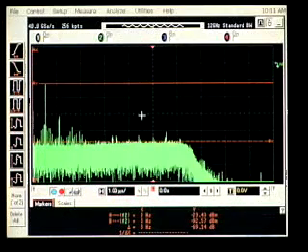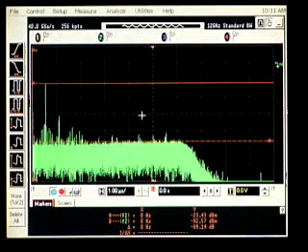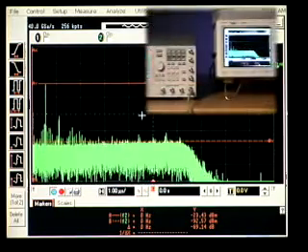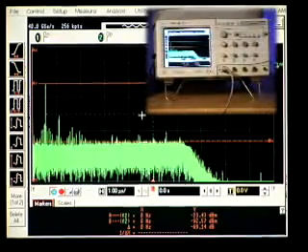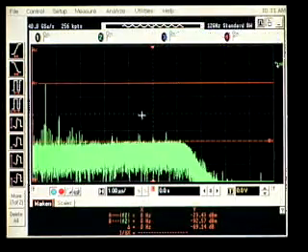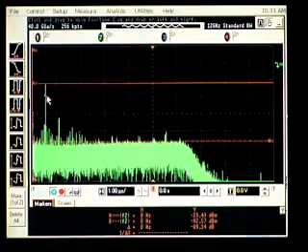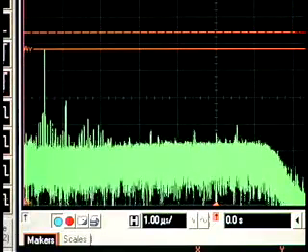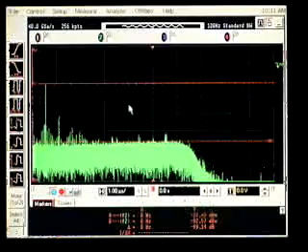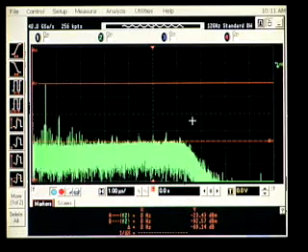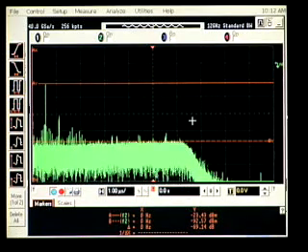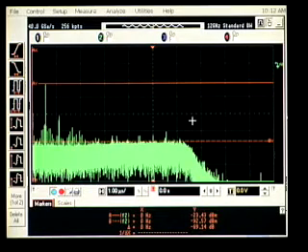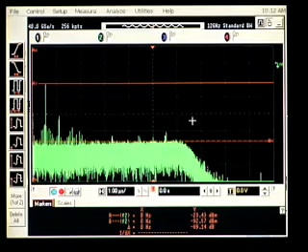What really matters, of course, is signal-to-noise ratio. So to look at that, I have inserted a 1.1 gigahertz full scale, that is 8 division peak-to-peak, signal into the channel. And now looking at the FFT again, you can see that spur right there, which is the 1.1 gigahertz input. We can put a marker on that, so then we can measure dB ratios for the noise and for the digitizing spikes. This will also allow us to look at a third component of unwanted or spurious information, and that is the harmonic